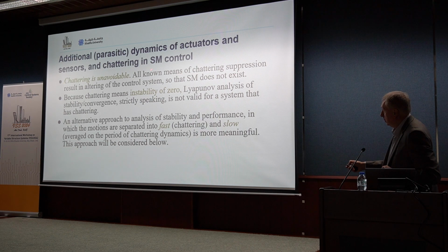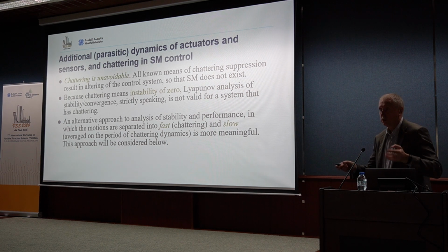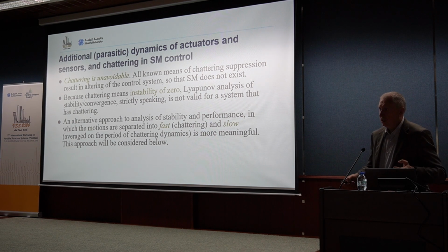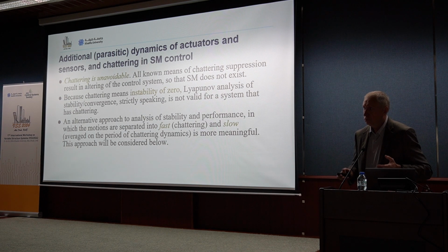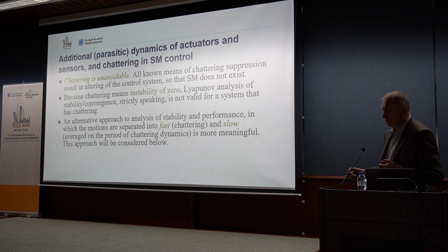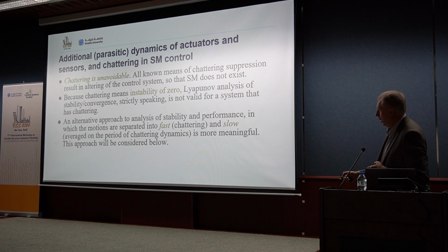Chattering is unavoidable, and because chattering is instability of zero, as I said, Lyapunov analysis of stability and convergence at least needs to be reassessed in terms of the applicability and the value of this analysis. What is then the alternative way to analyze this system? I would say that with the approach that we will develop, we can analyze it